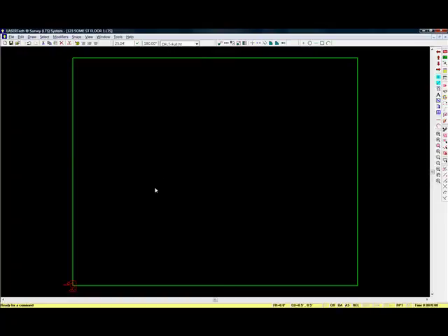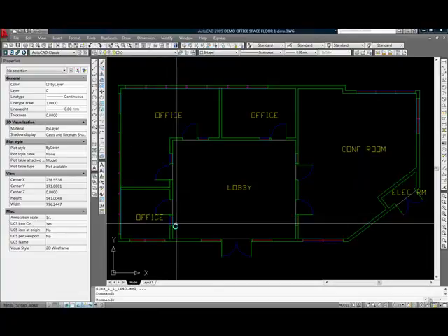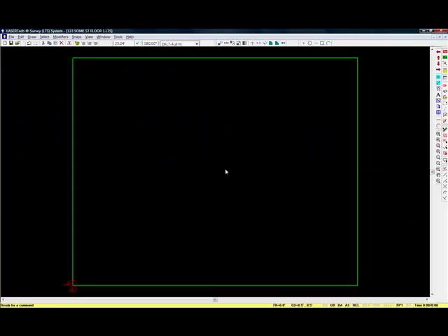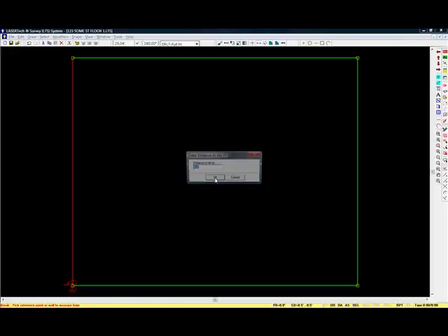And now the next step, if you go back to our AutoCAD drawing, you can see there's two doors in each wall. And the operator would put the doors in. And to do that, he uses what we call the break tool. And with that, he says, I'm going to break this wall. And where am I going to measure from? I'm going to measure from here. And he would disto that distance. And it's 5 feet, we'll say, and it's a 3-foot door opening. He actually measures the door opening.